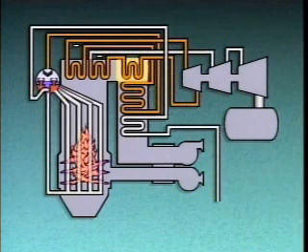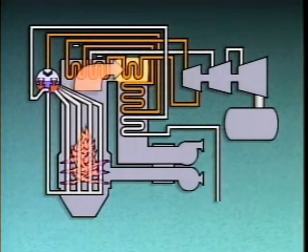The primary reheater is located farther from the flame, and it receives most of its heat by convection from the hot combustion gases, so it can be classified as a convection reheater.